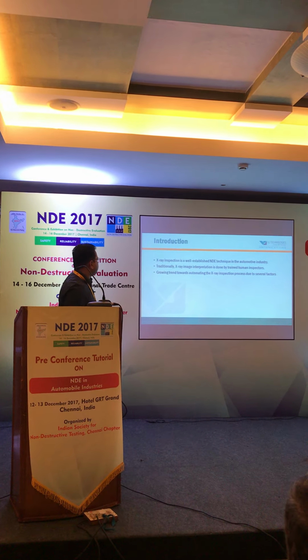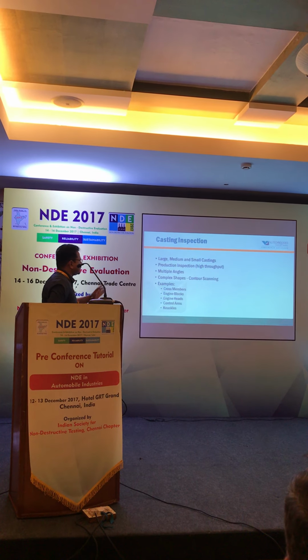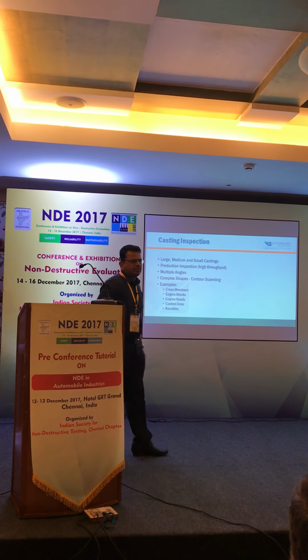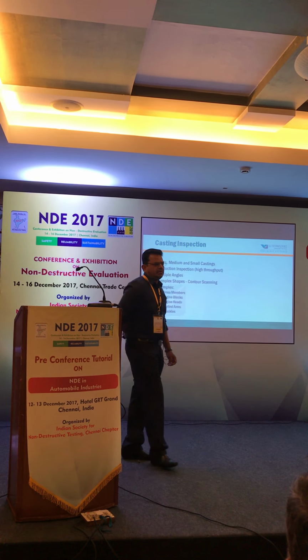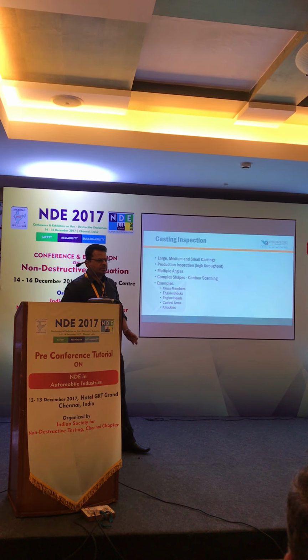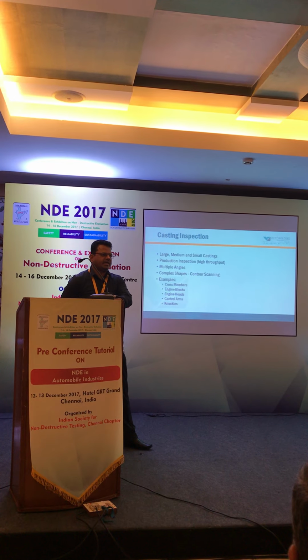And there is a growing trend of automating the X-ray system process, due to several factors. Digital X-ray technology has been introduced in large, medium, and small castings production inspection with high throughput, cycle time of 20 to 25 seconds, 25 to 30 seconds per part, from loading to rejection and acceptance.